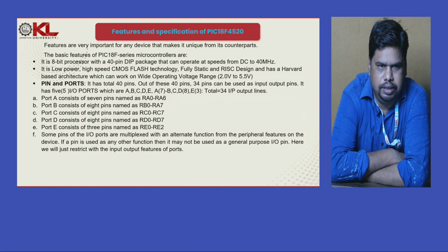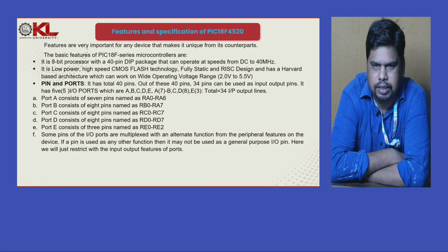So basically the 18F series is an 8-bit processor with a 40-pin DIP package that can operate at a speed from DC to 40 megahertz. It operates on low voltage. It has high speed CMOS flash technology, fully static and a RISC design, and has a Harvard based architecture which can work on a wide operating range from 2 volt to 5.5 volt.